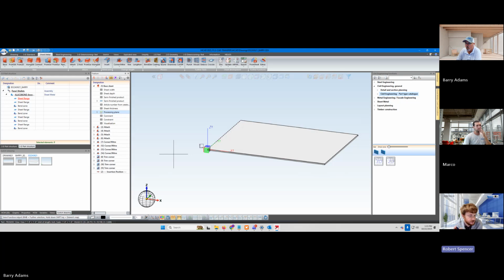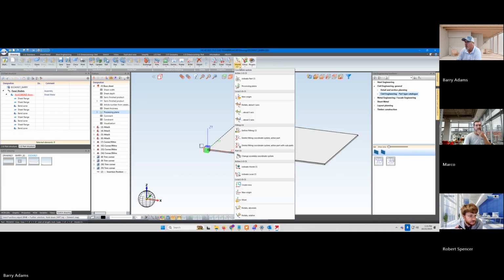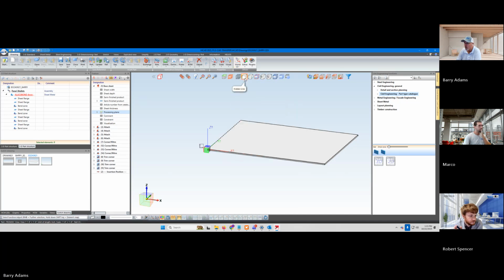Let's go up to the actual sheet metal main part in the structure. Where's that at? This one? The very top. Okay, now activate your part coordinate system. So drawing, ribbon, and then all the way over to the drop down under World CS and say Part CS, first one. That also looks okay.